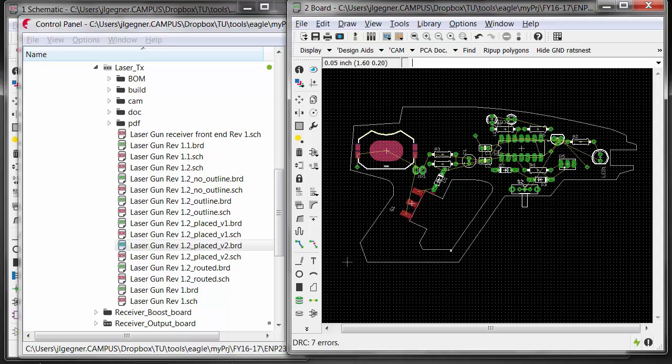So you can make a really simple rectangular PC board, but then maybe house it in something that's a little more shaped like a gun, using anything from cardboard to wood or anything else. As I mentioned, we can 3D print or laser cut, specifically laser cut some materials if you like. But you want to think about how you want to mount your circuit board in there. So maybe in your case you want to put some holes in your circuit board. You'll want to think about, should I use the circuit board to hold the switch that I'm going to be pushing, or whatever the case may be. But you should think through a design of the overall gun before you commit to a board outline and a component placement and then a routing.